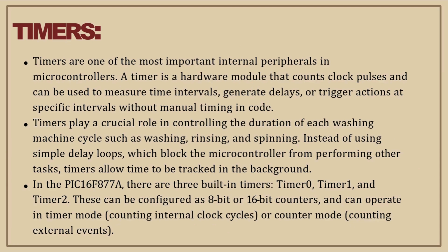Next peripheral, timers. Timers are one of the most important internal peripherals in microcontrollers. A timer is a hardware module that counts clock pulses and can be used to measure time intervals, generate delays, or trigger actions at specific intervals without manual timing in code. Timers play a crucial role in controlling the duration of each washing machine cycle, such as washing, rinsing, and spinning. Instead of using simple delay loops, which block the microcontroller from performing other tasks, timers allow time to be tracked in the background. In the PIC16F877A, there are three built-in timers: timer 0, timer 1, and timer 2.